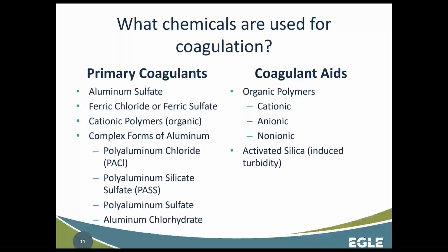Although anecdotally, I have spoken with operators at plants that feed powdered activated carbon in the spring or summer for taste and odor issues. And they have said that they get lower turbidities in the finished water when they're feeding that PAC. And they believe that it's probably because it does help increase the collisions and get better settling. And so there might be something to it, but a lot of folks have found that it's not necessary and it's kind of fallen out of favor.